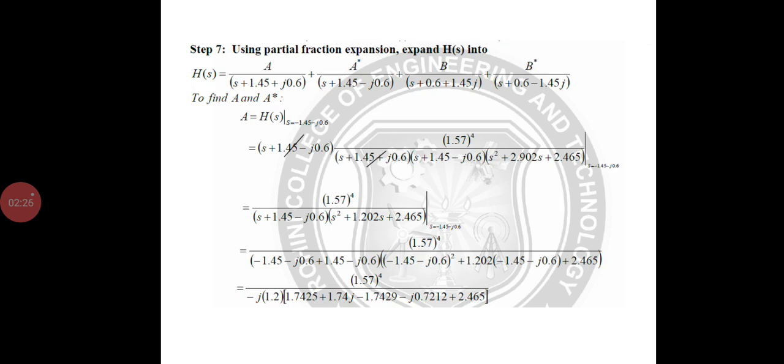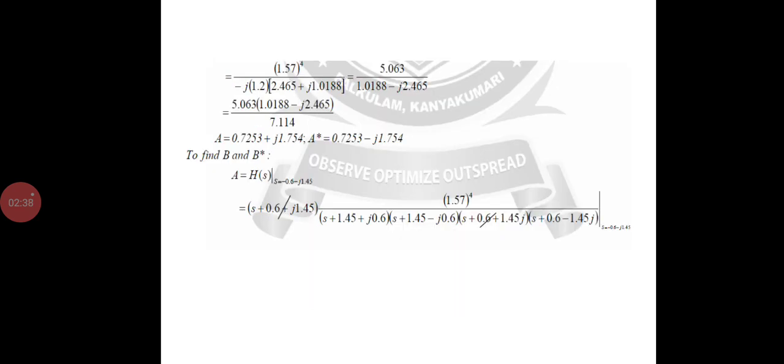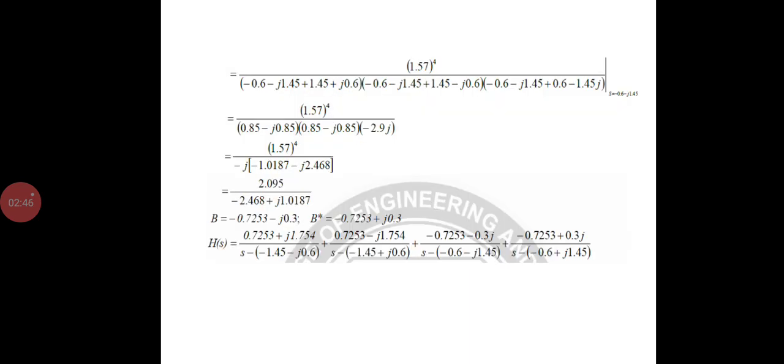Now they are asked to find it by using the impulse invariant method. Therefore, while we are performing this using the impulse invariant method, we want to perform the partial fraction expansion, and we are applying the partial fraction expansion. We are splitting the given expression into two or more terms, and after finding the values, we are adjusting the equation according to the formulas in the case of the impulse invariant method.